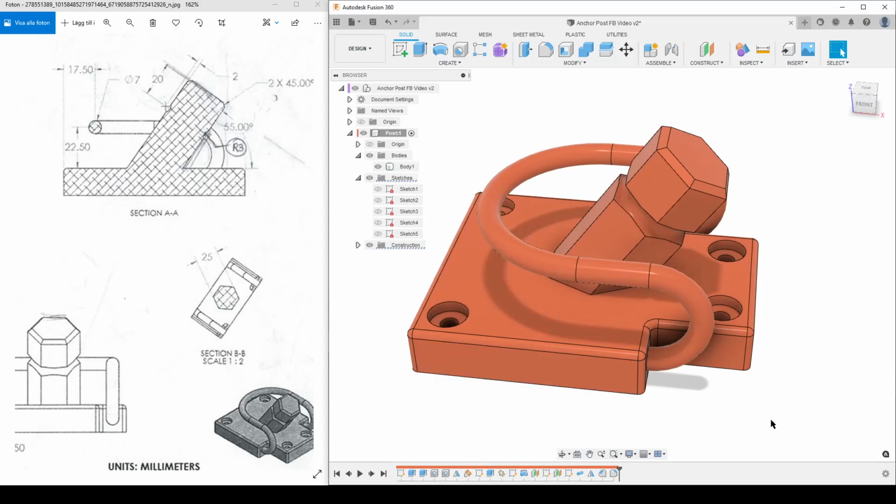And step number one, I know I did a revolve, so I know it's this one here, but if you have done something, you know, okay, it's the thing with this face here. Highlight the face by selecting it, clicking on it, and you see in the timeline you get 3 little marks down here. So this face is created with this feature here. And if you follow along in my early video, you know that I tried to put the feature directly after the sketch that is connected to a feature, or at least it might be like here. I have 2 features, but they are from this sketch here and working in this direction forward.